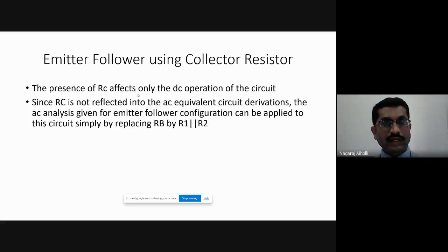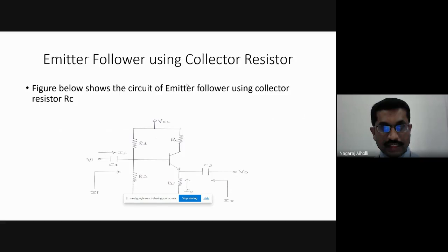The presence of a collector resistance affects only the DC analysis of the circuit. So this RC resistance which is present here affects only the DC analysis. It does not affect the AC analysis. I will tell the reason for that. This RC is affecting only the DC analysis.